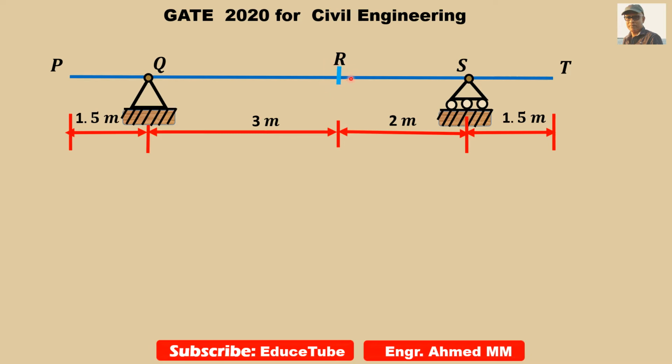This is a very important point to understand. That is why it is easier to conceptualize, because adding an internal hinge to the beam at this point easily releases the internal moment restraint.